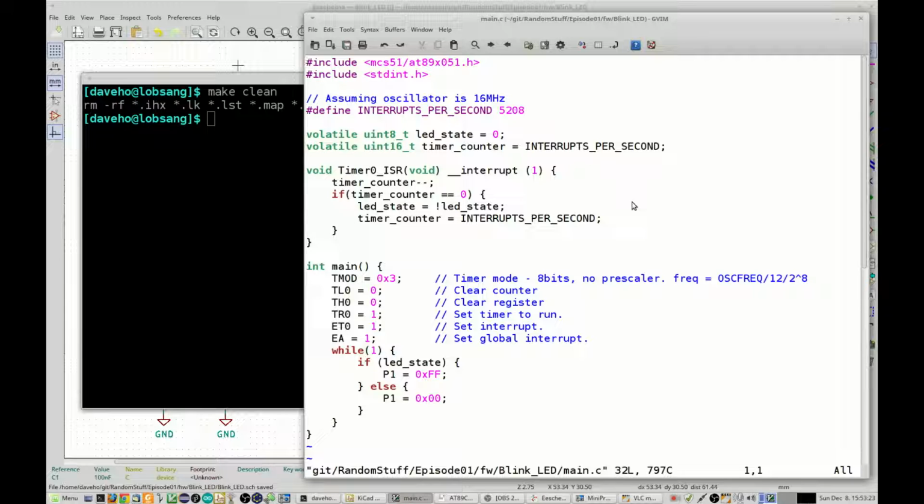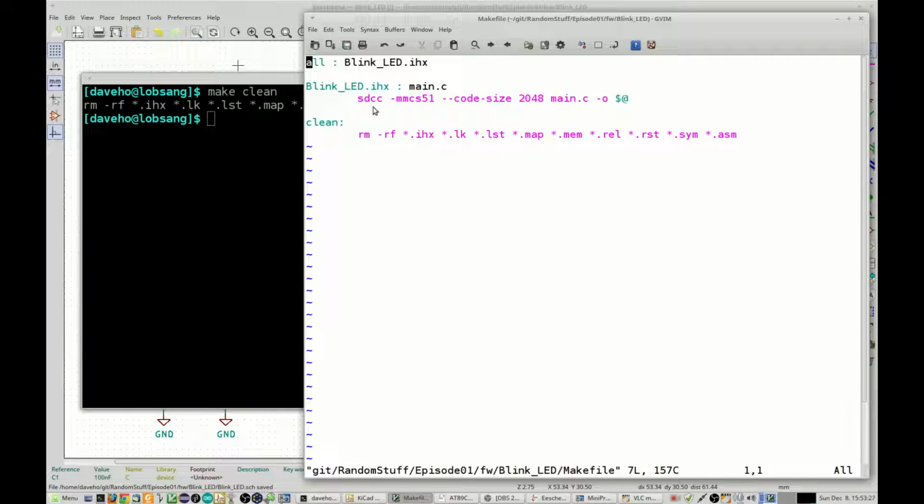All right, so to actually compile this C code, the makefile uses the SDCC compiler, and the target is an Intel hex file. Intel hex is basically a very simple text-based format that essentially specifies, for ranges of addresses, what specific byte values should be stored at those addresses, and it's a fairly common format for compiling code for these early embedded systems. And you can take your generated Intel hex file and burn it into your programmable memory device, or in this case we're going to burn it into the code data storage in the flash memory of our AT89C2051 device.